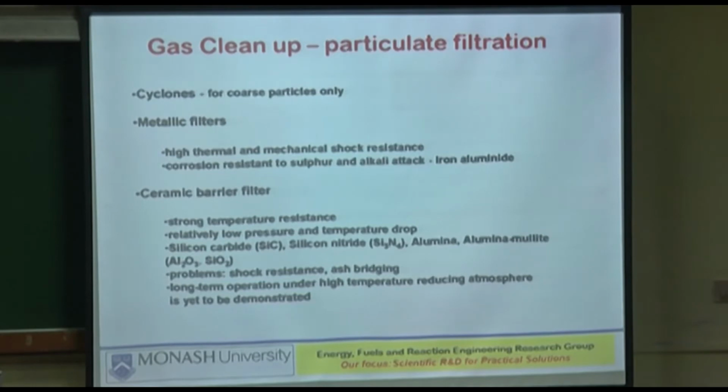So you then have to have other means separately, but at least what goes past the cyclone will not be as widely distributed as before. It will be narrower and finer, which means those lend themselves to separation by candle filters.